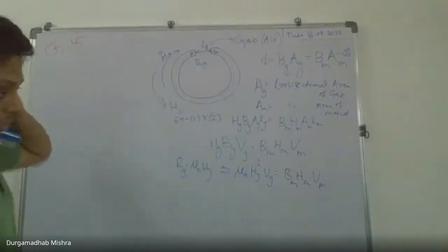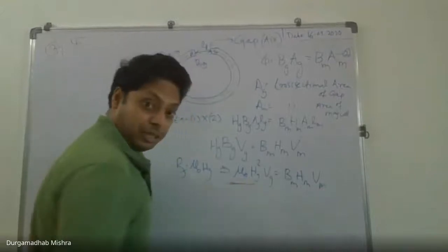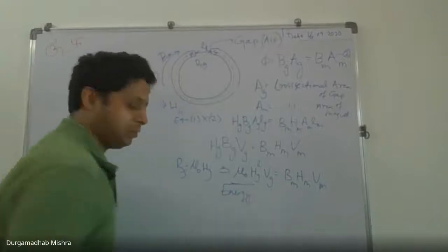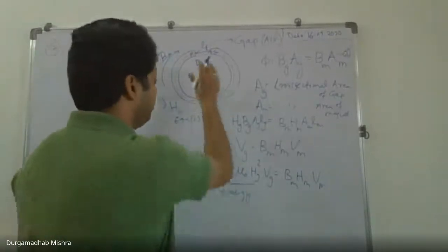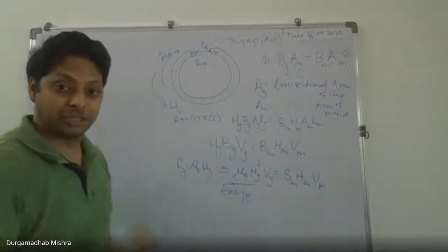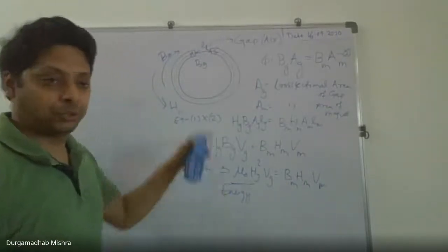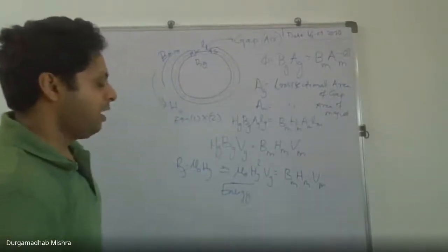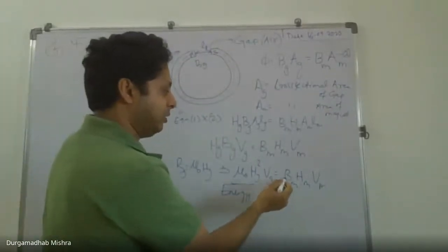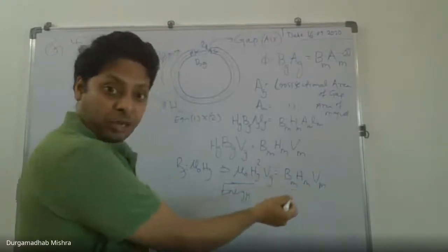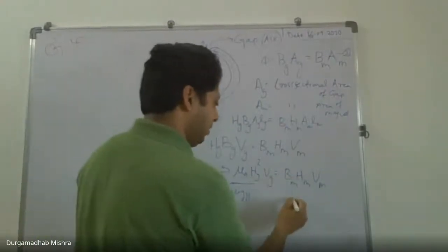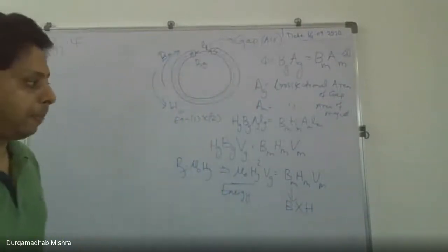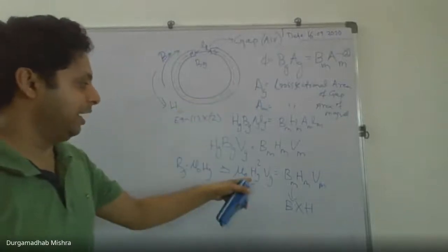This term is something like the energy stored in the gap. This quantity, mu naught Hg squared, is the energy stored within the gap in the volume Vg. Immediately what you see is that it is related to the product of B and H of the magnet, which is producing Hg.